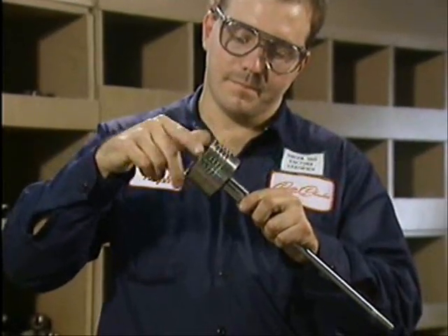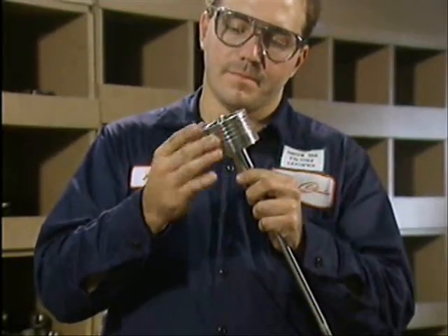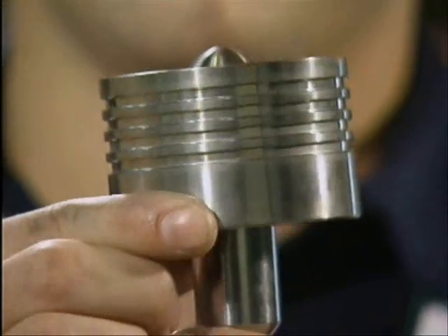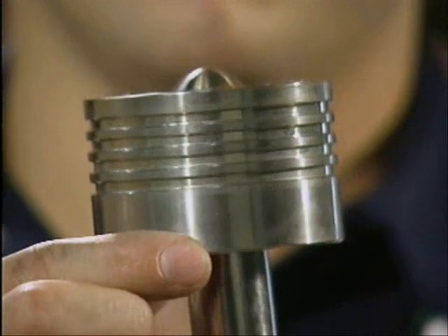The end of the stem that fits into the disc must be smooth and round, because it acts like a ball and socket joint inside the disc, so that the disc can align itself properly with the valve seat without damaging the stem. Flat spots on the disc end of the stem can cause uneven contact and unwanted friction between the stem and the disc.